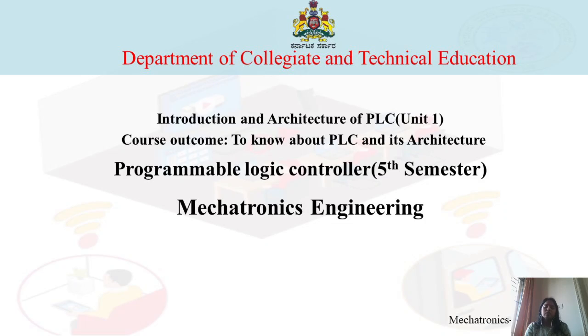The power supply has two different types, that is, internal power supply and external power supply. Internal power supply is provided to the CPU, because it needs less voltage, that is plus 5 volt to minus 5 volt. External power supply is for the IO modules. It may be 5 volt, 12 volt, 24 volt, 120 volt, etc. Then another component is your IO module.